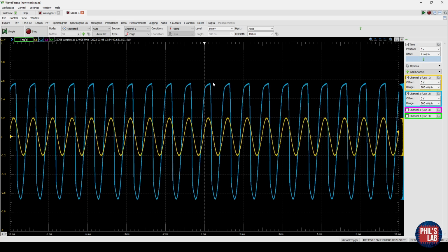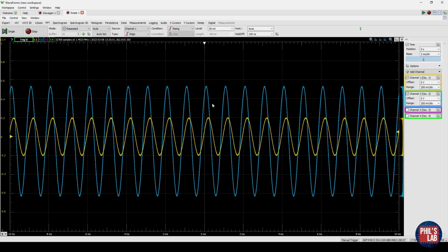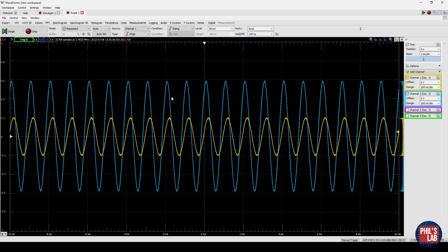And this of course isn't great because we get loads of harmonics in there, and our pure, well almost pure, 1 kHz sine wave at the output is rather distorted. This illustrates the fact that we do need quite a good bias supply, at least centered around the middle. So let's move it back to the center, and you can see we have a nice clean sine wave again.